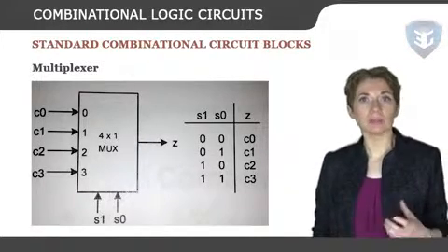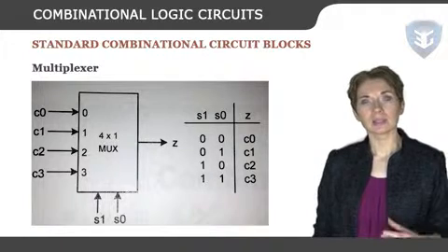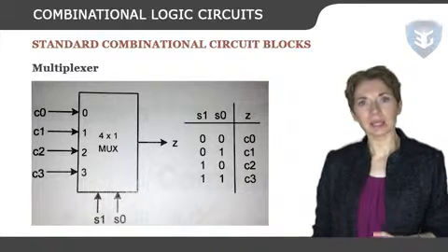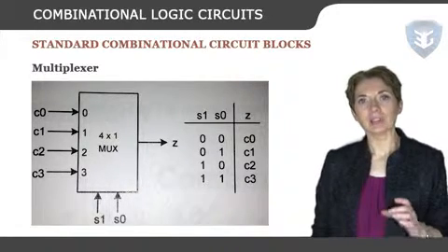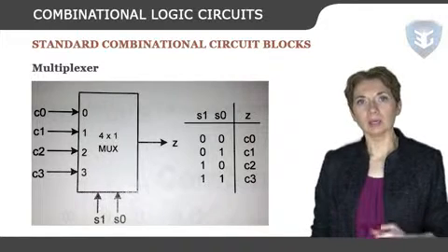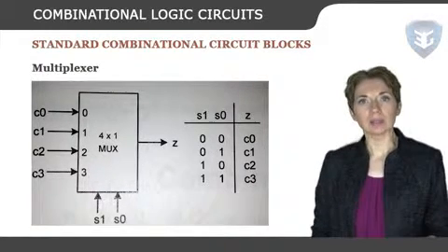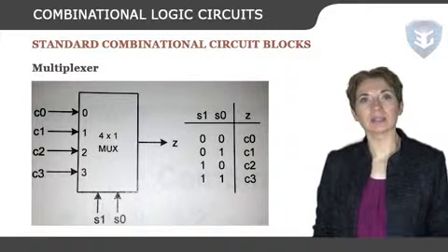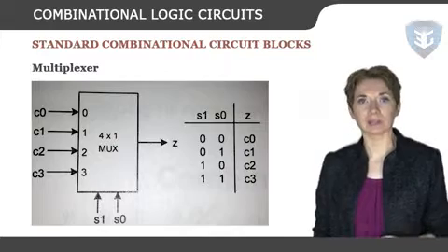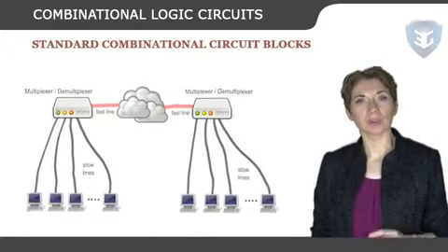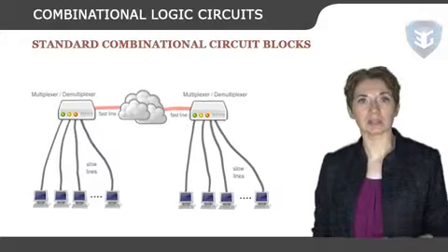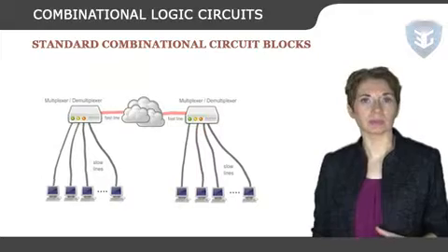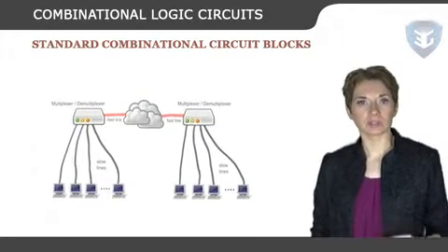Multiplexers also are used in building digital semiconductors, such as central processing units or CPUs and graphics controllers. In these applications, the number of inputs is generally a multiple of 2. The number of outputs is either 1 or a relatively small multiple of 2. And the number of control signals is related to the combined number of inputs and outputs. Multiplexers also are used in communications. A telephone network is an example of a very large virtual multiplexer that is built from many smaller discrete ones.